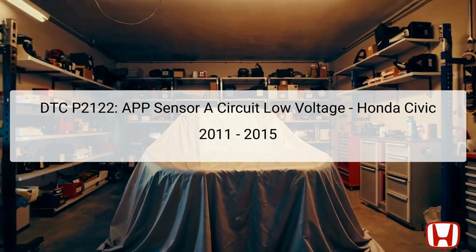The APP sensor, typically located on the accelerator pedal assembly, sends voltage readings that the ECM uses to regulate the engine's throttle response. When the sensor's voltage drops below acceptable levels, it triggers the P2122 code, indicating a potential electrical issue with the sensor circuit. Proper diagnosis is critical, as ignoring this code may lead to poor engine performance or drivability issues.